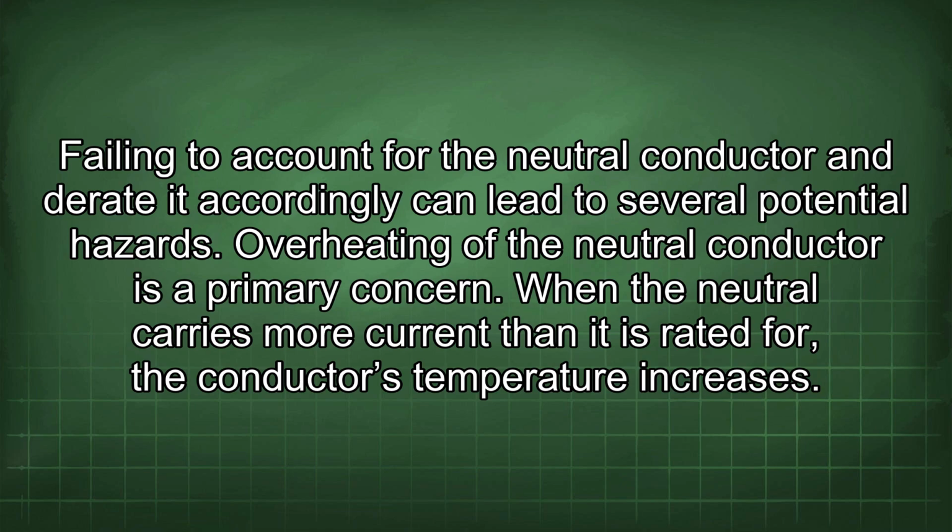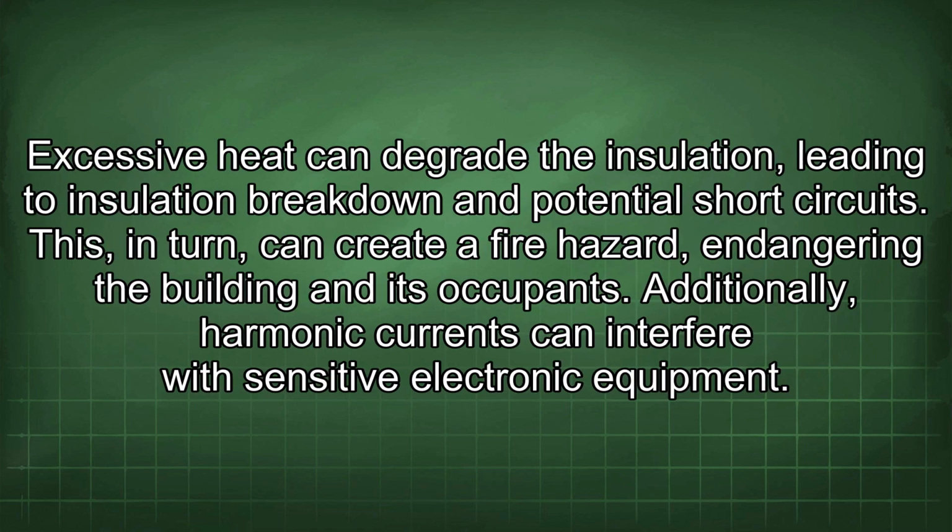Overheating of the neutral conductor is a primary concern. When the neutral carries more current than it is rated for, the conductor's temperature increases. Excessive heat can degrade the insulation, leading to insulation breakdown and potential short circuits. This, in turn, can create a fire hazard, endangering the building and its occupants.